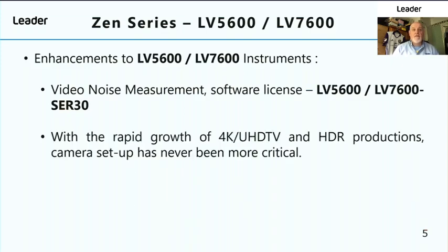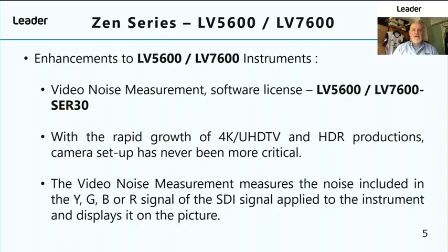And with the rapid growth of 4K, UHD TV and HDR productions, camera setup has never been more critical, especially in a multi-camera live production environment. So the video noise measurement measures the noise included in the Y, G, B and R signals of the SDI signal applied to the instrument and displays the measurement on the picture.